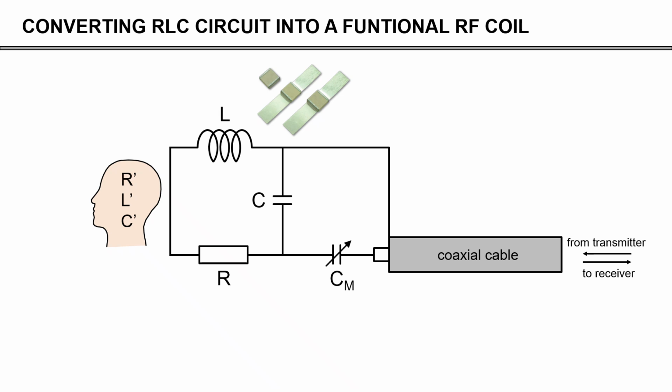So on the RF coil, the actual wire has some capacitance, but there's also so-called fixed capacitors, which are looking like this, and those have these parallel plates inside of them. But these are just fixed value. Once they are soldered in place, you cannot change them anymore. Here, this is a variable capacitor. They look a little different. You can see here, there is now a threaded screw here, where you can push it in or out, and that will change the capacitance value. And so we have a little bit of a range to deal with different samples.